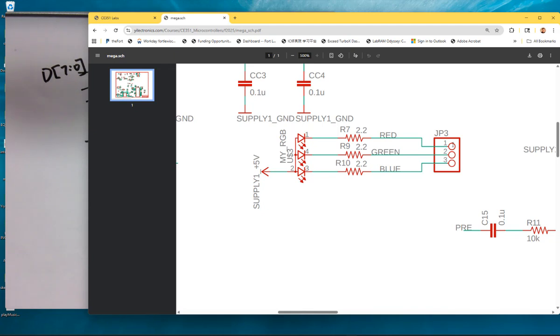And one thing I want to let you know is that you shouldn't directly look at the LED if you give it 255, which is full brightness. That's just too bright, because if you look at the current limiting resistor, it's only 2.2 ohms. We should actually use a bigger resistor. It's making the LED super bright. I would recommend using paper, like US letter paper, on top of the LED when you are programming it. Okay, it's hurting your eyes.